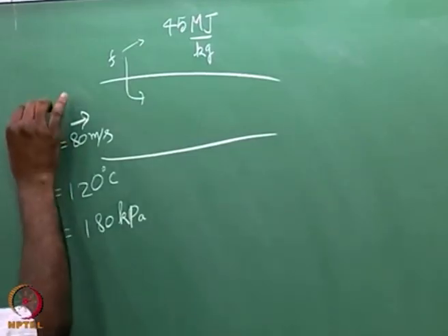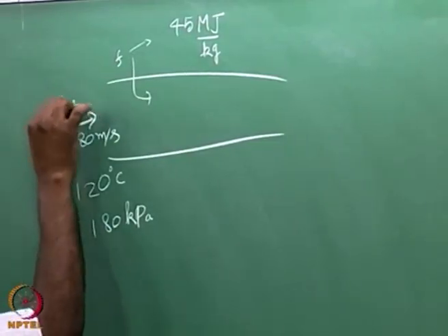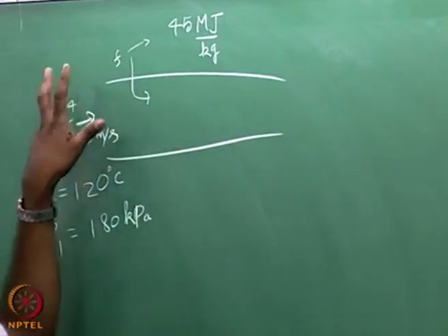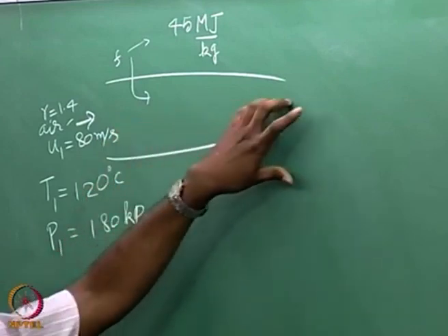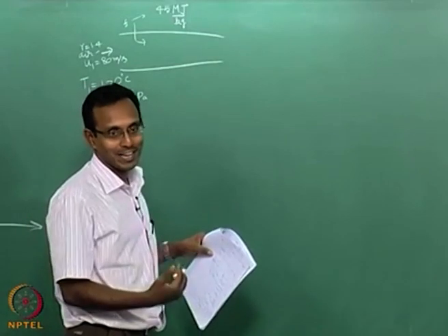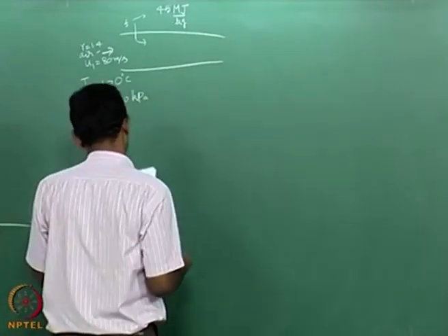And I am going to say this is air going in, gamma equal to 1.4 air. And I am going to assume that because of combustion, the gamma does not change, as I said in the beginning of the Rayleigh flow assumptions itself. Even though we know carbon dioxide has a different Cp value than air, we will assume that it does not change much.